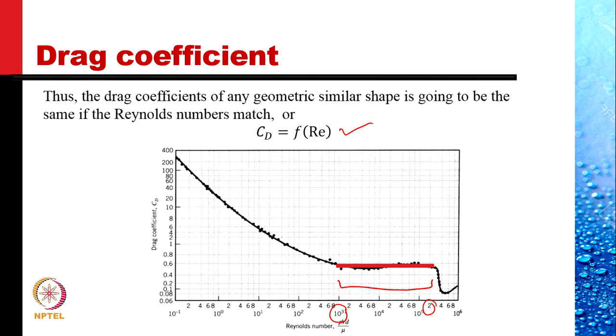In fact, testing it at the matching Reynolds number, which required a speed of 360 kilometers per hour, would create serious problems. The speed is so high that it is tending to be in the regime where compressible effects start becoming significant that we neglected. So if we measure drag coefficient at that large a speed, we may not get the right result.